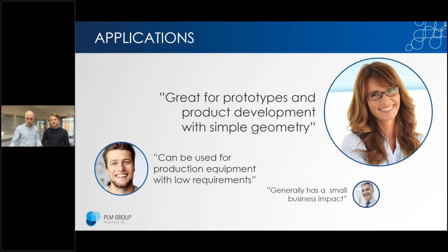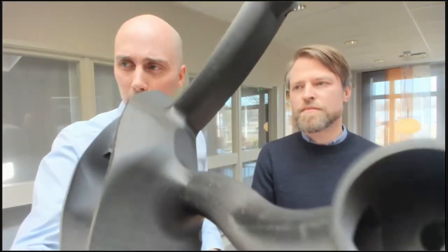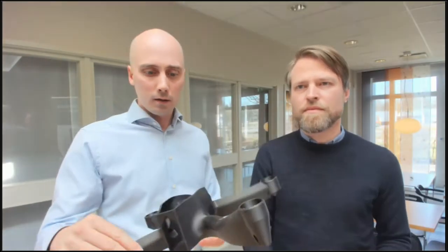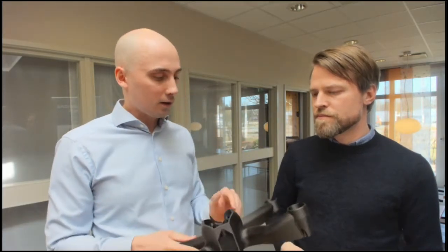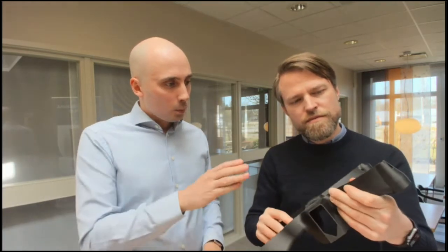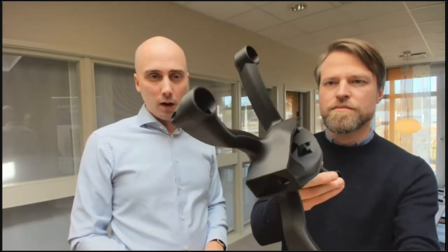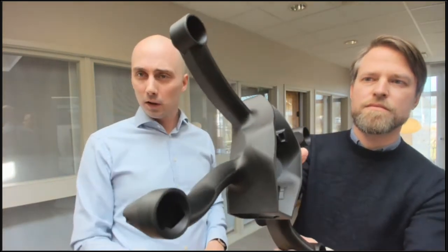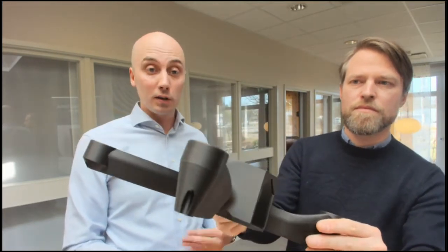So looking at some parts from an FFF technology, this is kind of the surface finish you get from an FFF machine. I mean, it's not bad. I'm not sure if you can see it on the screen. It's generally actually quite okay, but a low rating means that it's much worse than the other technologies. So if you want better surfaces, you should definitely not go for this machine. Excellent. This is printed on one of our printers called Markforged. The material is a carbon fiber filled nylon material, really popular for production equipment, so not only for prototyping and product development.